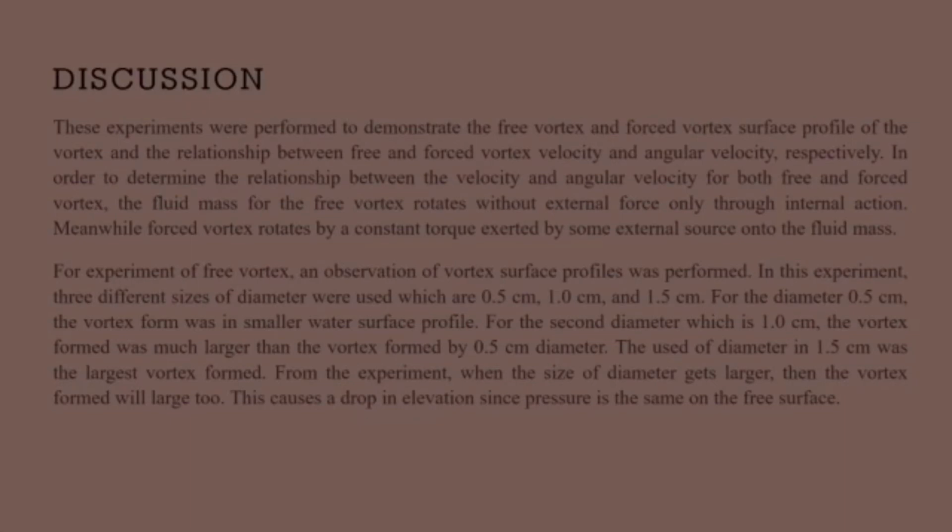Discussion. These experiments were performed to demonstrate the free vortex and force vortex surface profiles of the vortex and the relationship between free and force vortex velocity and angular velocity respectively. In order to determine the relationship between the velocity and angular velocity for both free and force vortex, the fluid mass for the free vortex rotates without external force only through internal action. Meanwhile, force vortex rotates by a constant torque exerted by some external source onto the fluid mass.